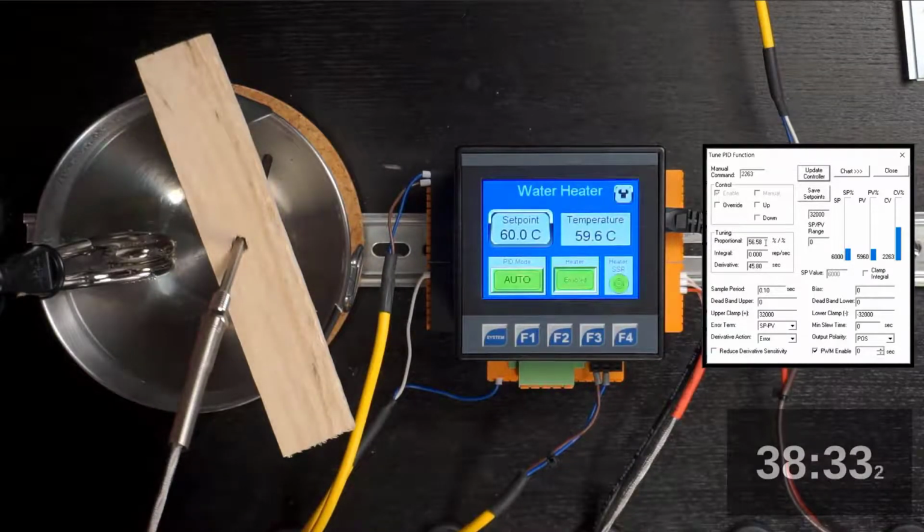So to summarize, for at least this reasonable tune where I'm plus or minus 0.7, I took the tuning parameters that were suggested or found during the auto tuning, and then after trying them out and seeing that we were unable to use those parameters exactly, I basically zeroed out the integral term because it was pretty obvious that we were in a runaway situation both directions.